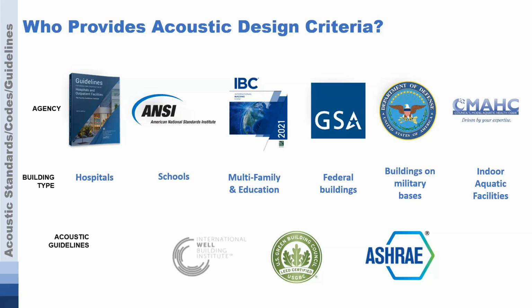Multifamily and education, obviously the International Building Code and Florida Building Code have criteria for residential sounds for STC and IIC ratings. And the GSA also provides guidelines for federal office buildings, courthouses, etc., looking at STCs, RTs, and NCs. The United Facilities Code, the UFC, also addresses buildings on military bases. And so whether it's offices, schools, training facilities, and fitness centers, all of those have acoustic criteria.